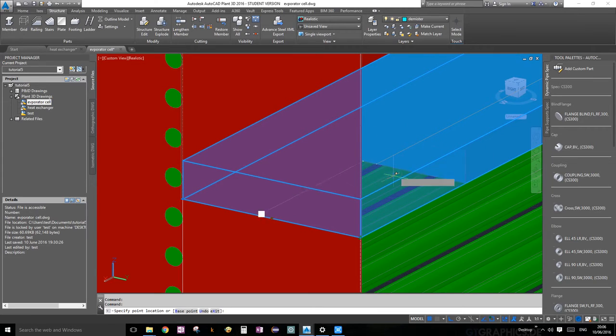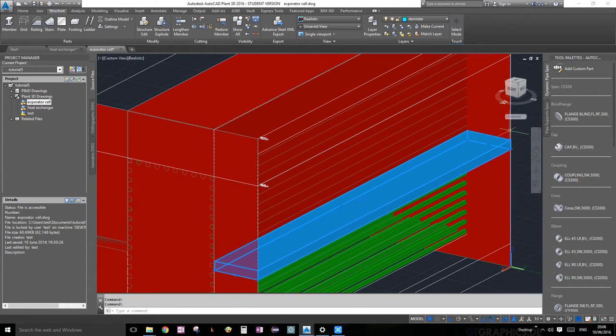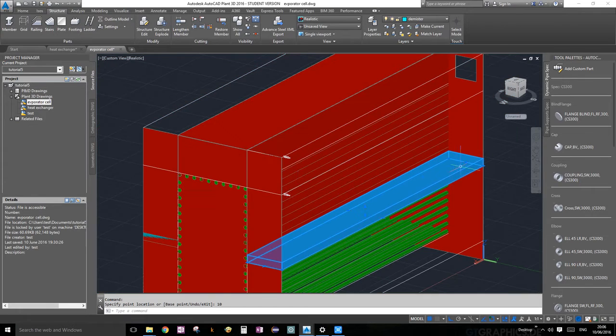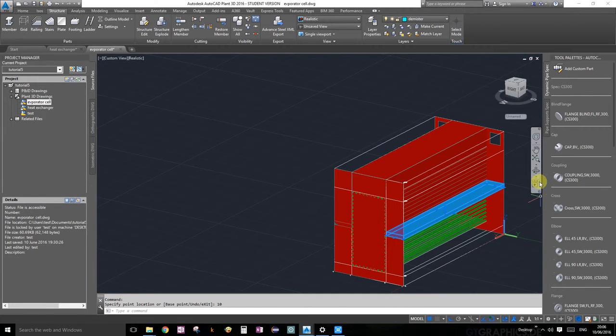You can also adjust, in any direction, the thickness, height, or width. I just want it to be shorter by 10 millimeters because I wanted to miss the plate. So 10 millimeters. Now it won't show through. Going to do that on the other side as well. So we're going to go 10 millimeters, fixed, and we can also do it to the other side.